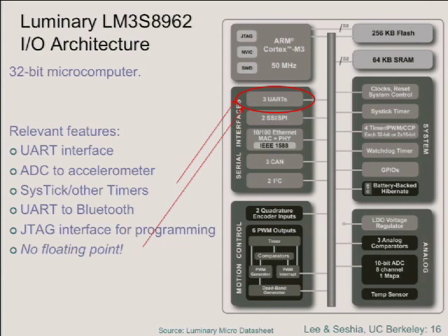You're going to be getting interrupts on each of these lines at extremely high rates. Can you context switch quickly enough to take advantage of that? Probably not. The context switch cost is going to be much higher. So I think that could work if you had a multi-core architecture, with a separate processor on each end of these wires, but it'd be hard to use where you're multiplexing a bunch of threads on a single core. Context switches are actually quite expensive. They take many, many cycles to execute.